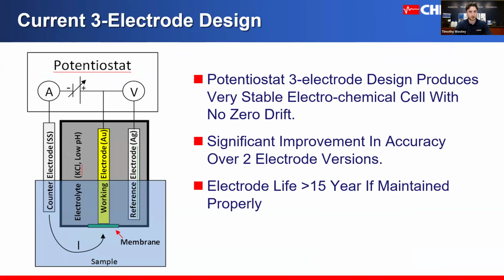So here's the 3-electrode design again. It uses that potentiostat 3-electrode design, and it is a very stable reaction that has virtually zero drift. This has a significant improvement in accuracy and a much longer life of the electrodes. We still have this technology that's been out in the field for over 15 years and is still working accurately, with just proper maintenance and proper exchange of the membrane and the electrolyte. This long life is a huge practical benefit to operators or anyone working with these probes out in the field.